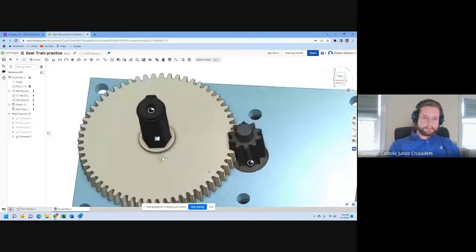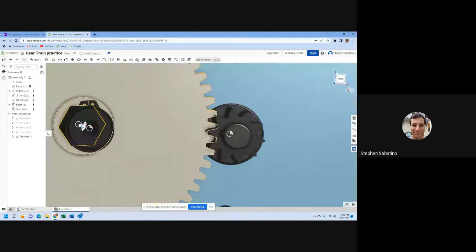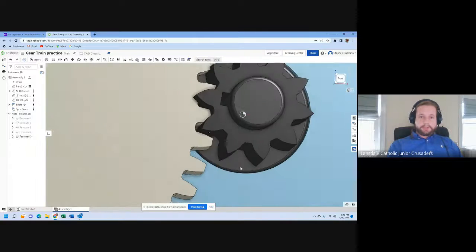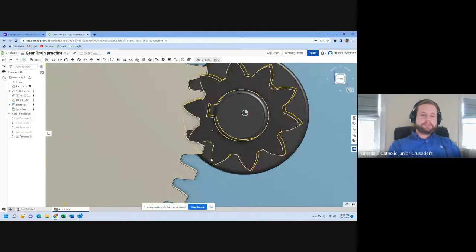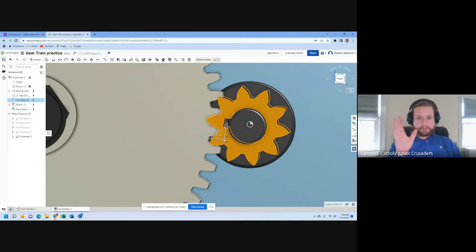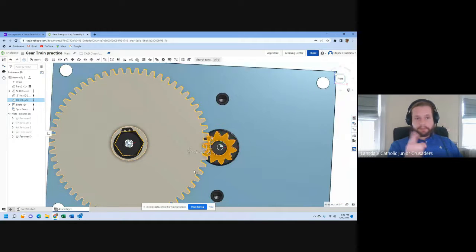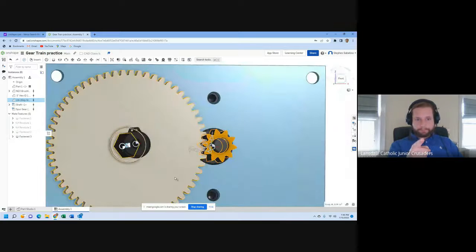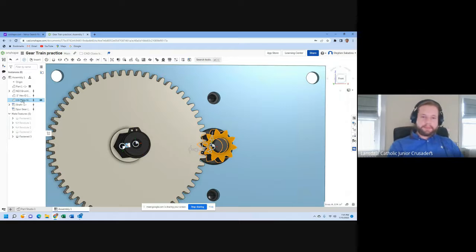Okay. Cool. Did I pick the wrong spur gear? So these spur gears, some of the new spur gears that have a lesser tooth count, use a larger center to center distance. And they do this by kind of messing with the geometry of the tooth. So you can use that one, but you have to change your center to center tooth distance. And you might have to look up the manufacturer's information on that. So I believe that's a Rev gear, or it might be a Vex gear.